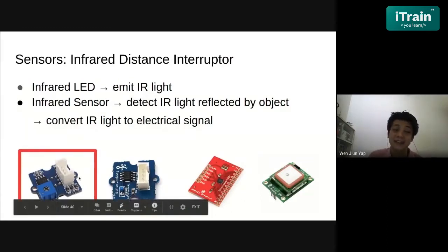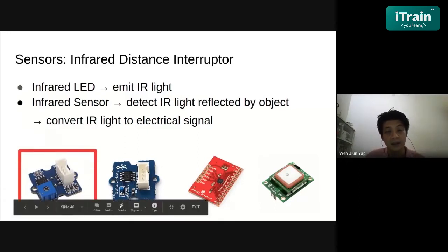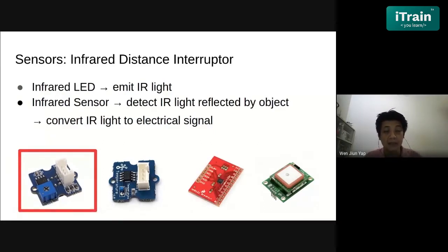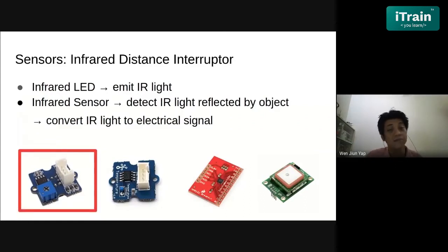So what does this sensor actually function as? If you put it on a conveyor belt, like when you go to eat sushi, the belt that is moving around, you can put the sensor at the entrance or the exit of the belt, and it can start counting how many objects pass by. Any object passing by reflects the infrared back to the sensor, and the electrical signal changes, which you can detect and process, and tell there's one object passing by. So you can start creating counts of how many sushi are being eaten every round and so on.